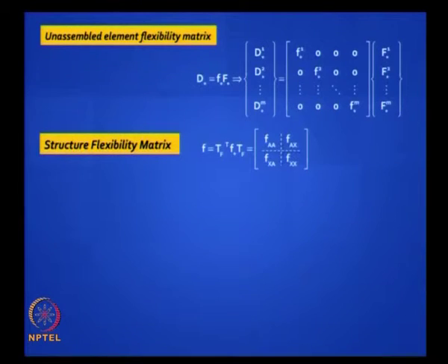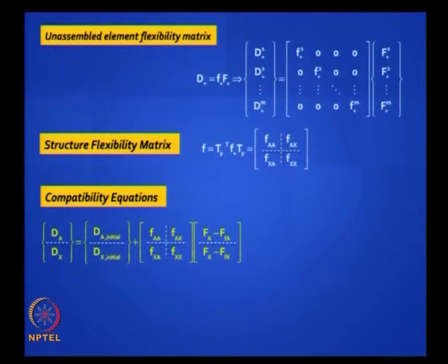Now what is the equation that you need to solve? It is a compatibility equation. Without this you cannot get the X. Now you have to satisfy compatibility at the active degrees of freedom and also at the redundant coordinates. So this is pretty simple to understand. dA, dX is equal to dA initial, dX initial, in case you have some initial displacements like this lack of fit problem that we had, plus this flexibility matrix into what is sometimes referred to as the net load vector.